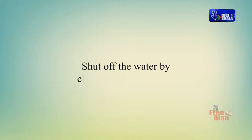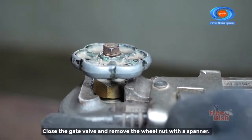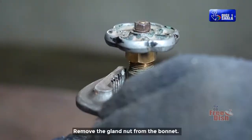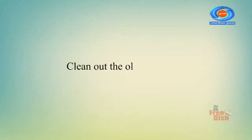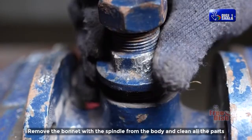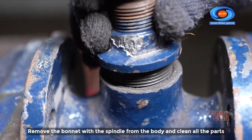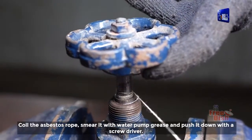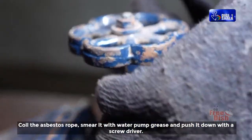Shut off the water by closing the main valve. Close the gate valve and remove the wheel nut with a spanner. Remove the gland nut from the bonnet. Clean out the old packing in the stuffing box. Remove the bonnet with the spindle from the body and clean all the parts. Coil the asbestos rope, smear it with water pump grease and push it down with a screwdriver.